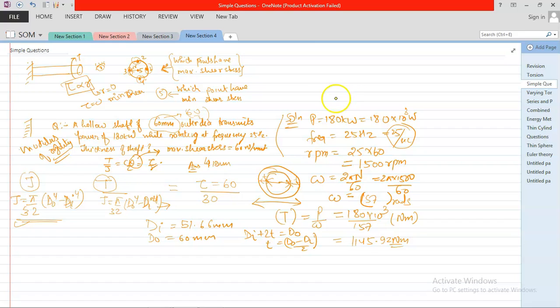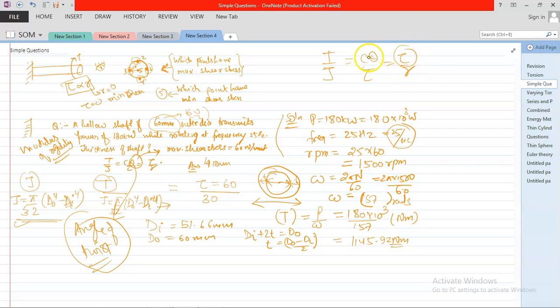Now if you are given the value of modulus of rigidity, you can also find the theta, means angle of twist in the body. So it is just a game of what is given and what you need to obtain. Suppose this is your equation, you can obtain shear stress if your C is given, your length is given, torque is given, J is given.